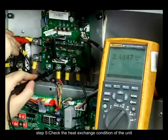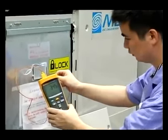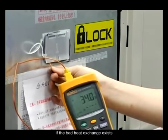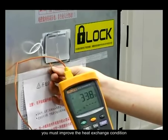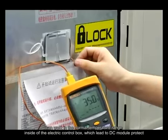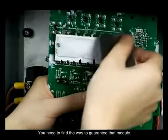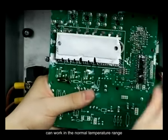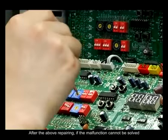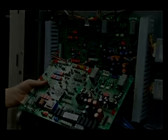Step 5. Check the heat exchange condition of the unit. Bad heat exchange will lead to high temperature inside the electronic control box, which can lead to DC module protection. If bad heat exchange exists, you must improve the heat exchange condition and find a way to guarantee that the DC module can work in the normal temperature range. For example, wipe the thermal silicone grease well. After the above repairs, if the malfunction cannot be solved, the PC board must be broken. You have to replace it with a new one.